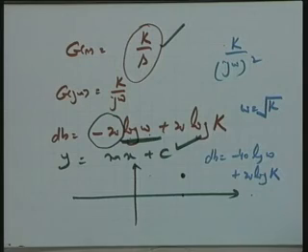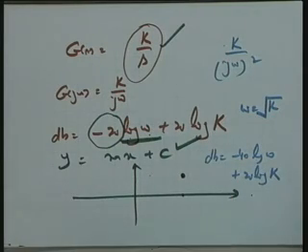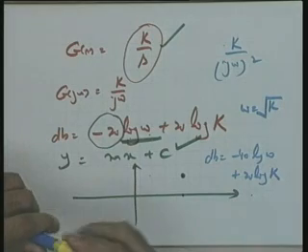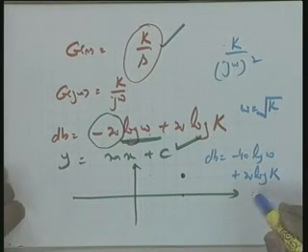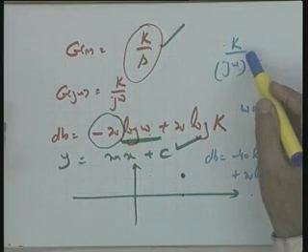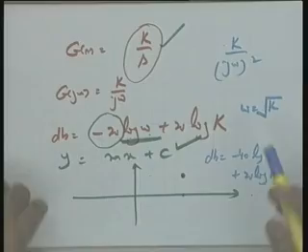So it means either you take omega equal to 1, locate the point 20 log k, and now the line is minus 40 dBs per decade, or omega equal to root k as has been told, and your line should pass through that point. I hope it is clear, and it may increase to 3, 4, 5, but as I told you, normally we come across type 0, type 1 and type 2 systems. And interestingly, let me make a mention here itself,